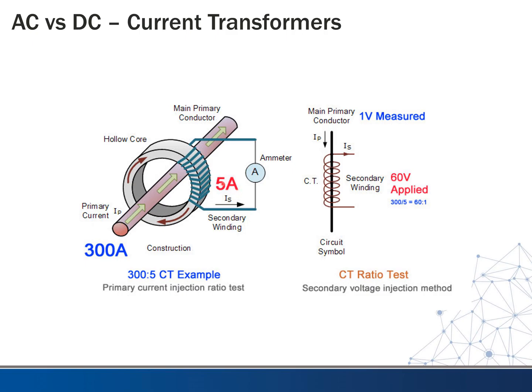So what they do is they use CTs, or current transformers, and they run the service conductors through here, and then it steps it down. So if you were to have a 3,000 amp service, I really only need to measure 50 amps out here, which is much more manageable. For the power company, it makes more sense.